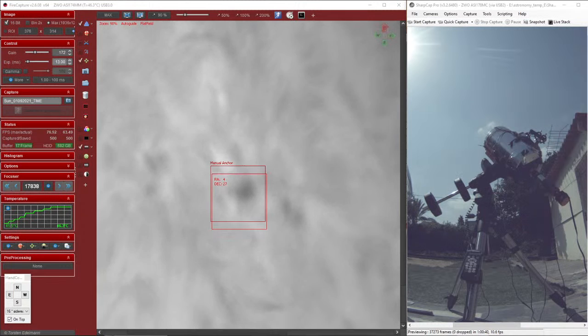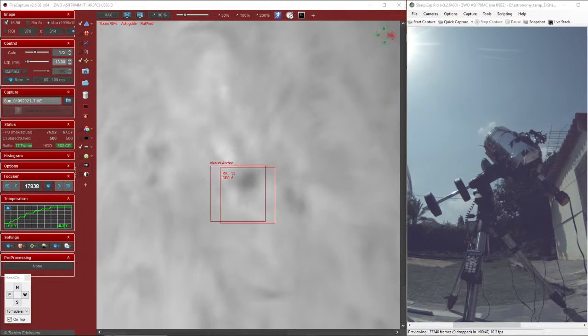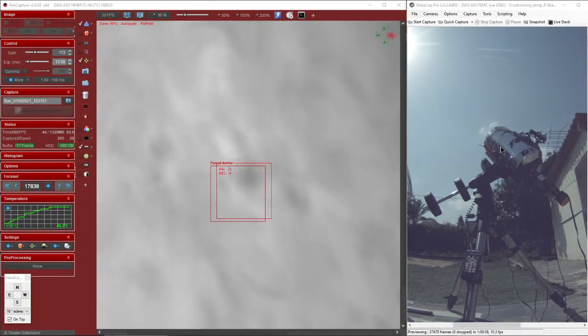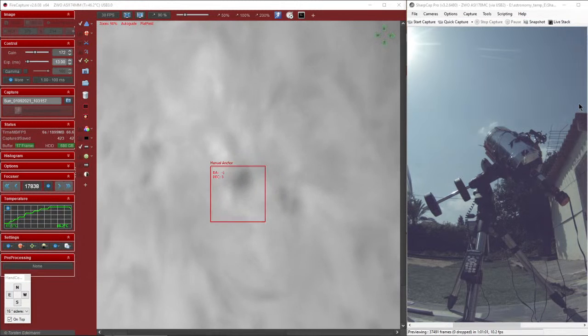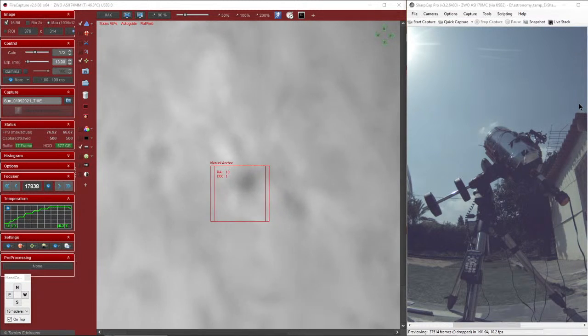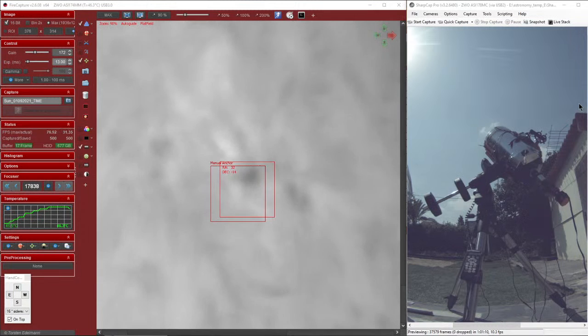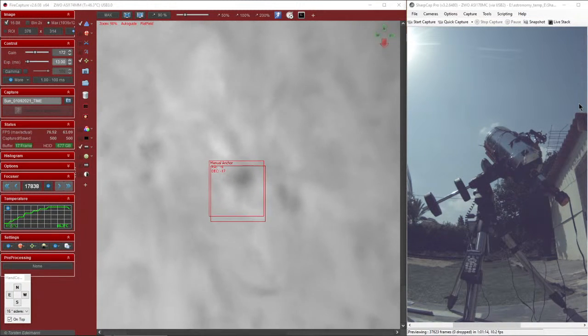So I connected all the cameras that are outside, and it couldn't handle that much data. When I connected the camera to the other camera too, it just disconnected everything. So I had to run another cable outside, and that happens all the time, because it's very hard to find a good cable that is 20 meters or 15 meters long, especially for USB 3.